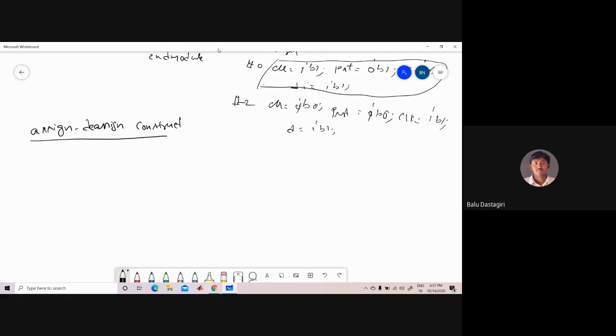The assign, deassign statements allow continuous assignments in a behavioral block. What we have seen so far in the behavioral model is only the procedural assignment statements. But by using the assign, deassign construct, it allows continuous statements within the behavioral block.